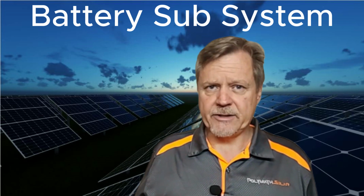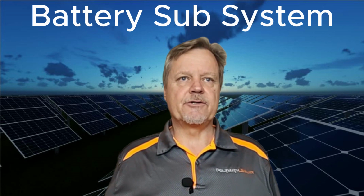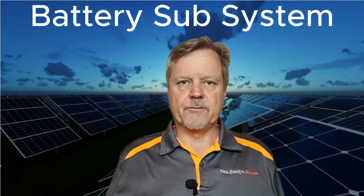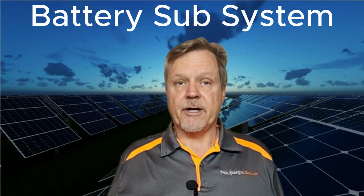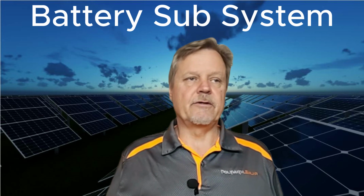Okay, so let's talk about battery capacity. So what if the battery is too big? If the battery is too big, again, no big issue. It'll take longer to recharge it. So if you recharge it with your grid utility, with Eskom power, it'll take a little bit longer, depending on the charging capacity of your inverter. It'll take a little bit longer to recharge the battery, but you've then got a bigger fuel tank.